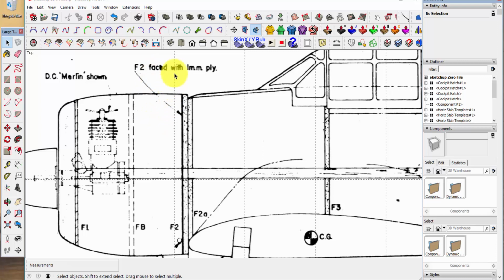So what we're going to do is call this good, because we're going to have to take this last former segment here anyway, our fuselage foam segment, and we're going to have a solid nose block here. Some of these back here are going to be hollowed out. However, this segment right behind the firewall is going to be solid, and we need about 20 millimeters of that to be solid. So what we're going to do now is take this front one and we're going to back it up 20 millimeters to right there.